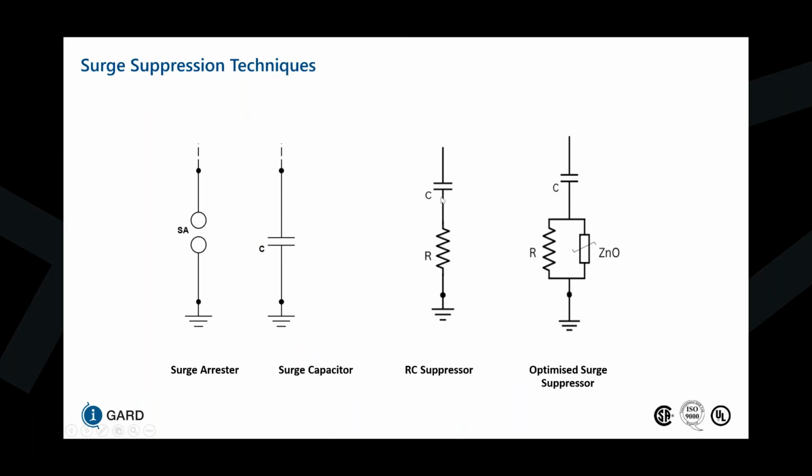The capacitance is typically ahead of the resistor so that you can block out this resistor from impacting during normal operation. And then when the capacitance is seen as a short, when the transient's coming through, then this resistor will be able to limit the magnitude of that transient and bring it towards ground to be dissipated.